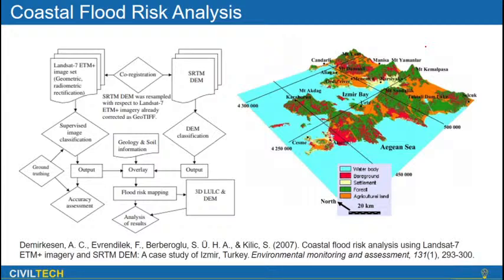So then you want to analyze how the land use pattern, or how the city, has grown over the years. That will help you to identify which particular locality is at a higher elevation or at a lower elevation. That will help you find out which region is prone to floods, right?